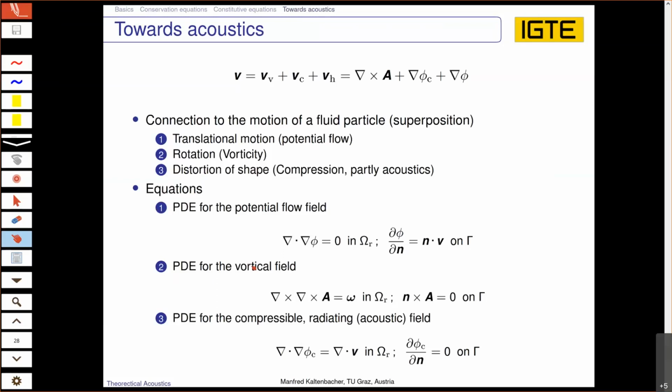So it makes sense not to solve the full set of compressible fluid dynamics equations on the whole domain, but just restrict these equations to a smaller domain, find physical models for the sources, which we can then use in a wave propagation model where we just solve for the acoustic field.